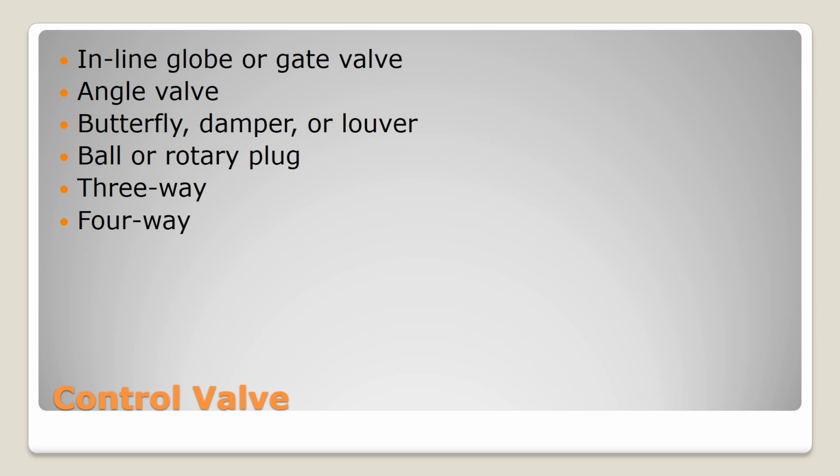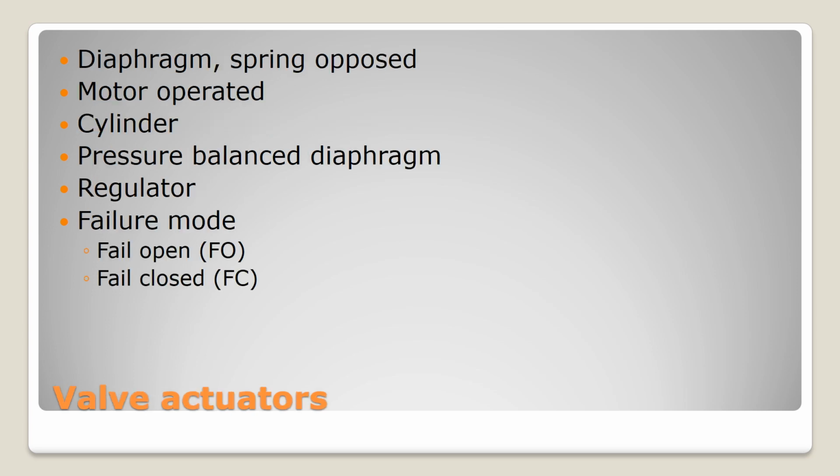We can connect those valves to a valve actuator. And a valve actuator is just a device that is going to use some kind of signal, some sort of remote signal, to operate those valves. And those valve actuators can be diaphragm operated, they can be air operated, they can be pneumatically operated with mechanical assists like springs, or they can be hydraulically operated. A lot of different types. So we're going to look at one here that's pretty typical.